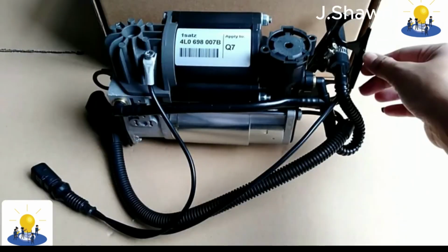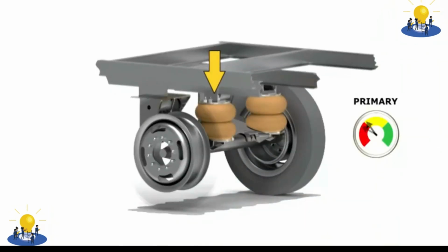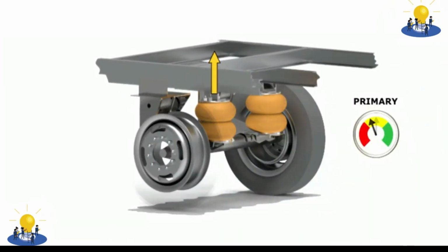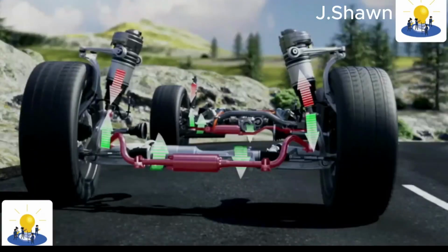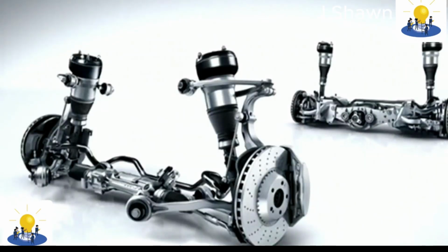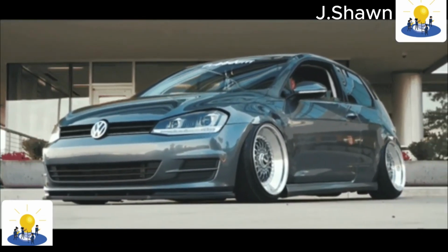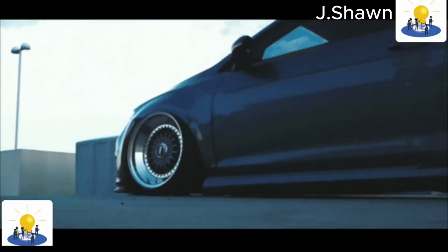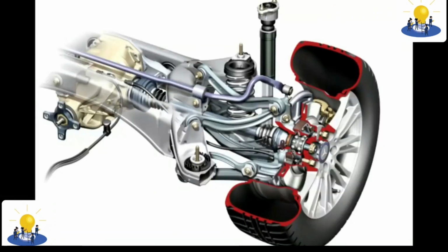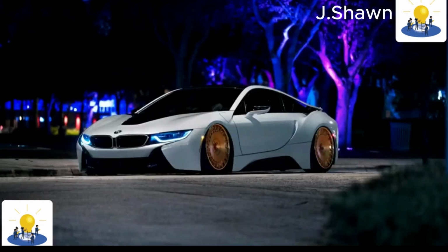The compressor will burn out trying to maintain the correct air pressure in a leaking air system. Compressor burnout may also be caused by moisture from within the air system coming into contact with its electronic parts. This is far more likely to occur with low-specification compressors with insufficient duty cycle, which are often purchased due to low cost. For redundancy in the system, two compressors are often a better option. In dryer failure, the dryer, which functions to remove moisture from the air system, eventually becomes saturated and unable to perform that function. This causes moisture to build up in the system and can result in damaged air springs and/or a burned-out compressor.